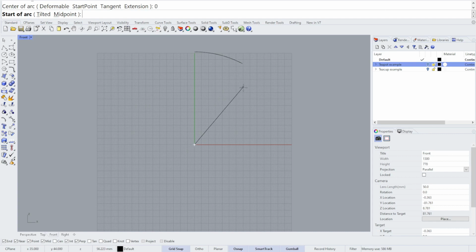To do this, we have to turn on the O-snap toggle. So here at the bottom you have this toggle called O-snap, which helps you snap to objects. If you turn it on, you get this extra row of options, and make sure that at least end is selected, so you can snap to the end of your first curve and continue the arc from there.